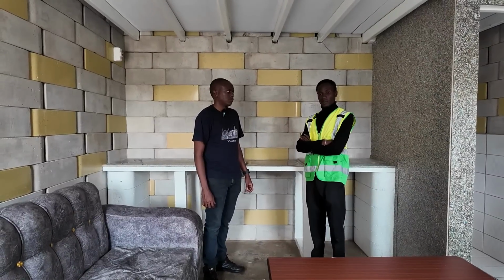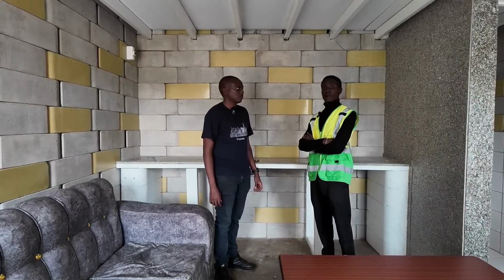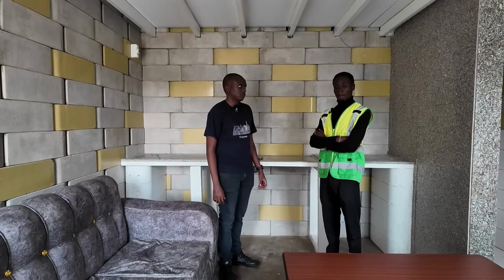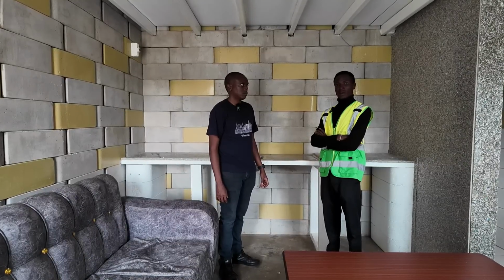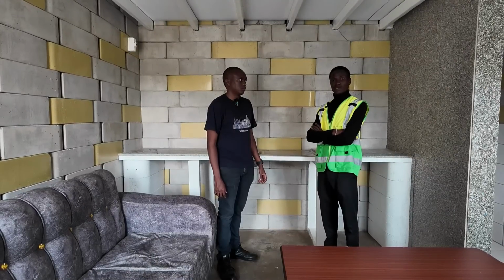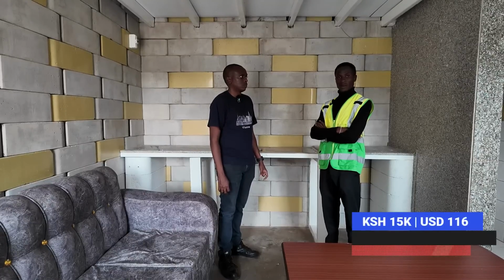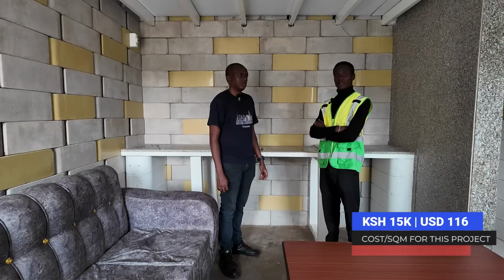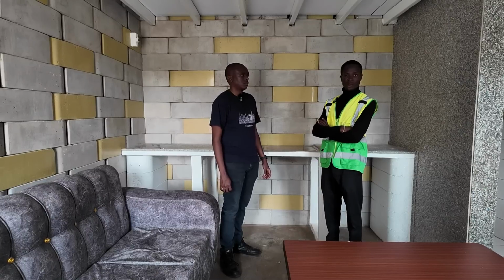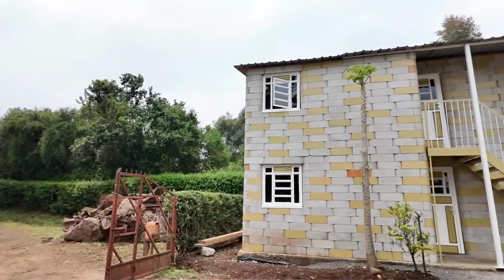Going back to the initial costing, the final costing for this project, which was rather 1.1 million Kenya shillings per floor area, that is 72 square meters, you'll be able to achieve a cost of around 15,000 per square meter. So our costing per square meter, which is directly proportional to the floor area, is 15K for this project, and it's a very simple project without reinforced concrete for the columns, and we're able to achieve a very, very good figure, that is 15K per square meter.